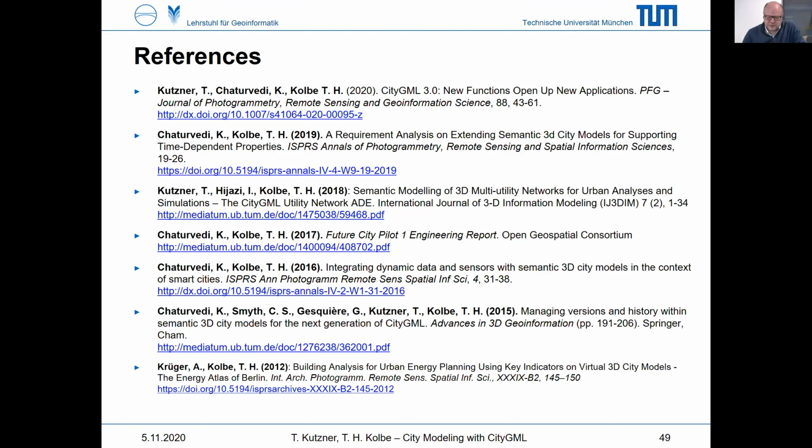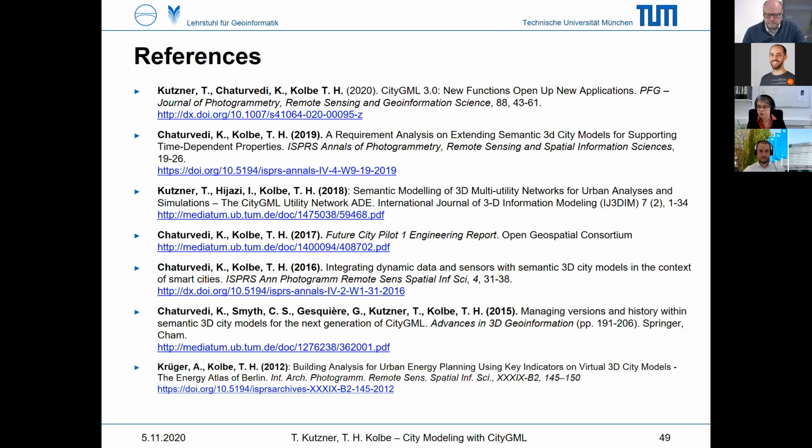It's also a topic that there are of course two things. There are the standards, but there are also the conventions, how they are being used. What is your view at the moment, which side is the bigger problem in the interoperability or conversions from IFC to CityGML? Is it the standard itself, or is it just the usage conventions of the IFC models? I think it's the standards, also the way of representing geometry. So in IFC you have the volumetric objects, and in CityGML, you have the boundary representations. And I think this, for example, is a huge problem.